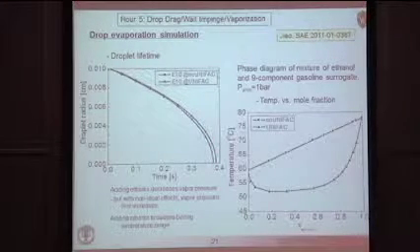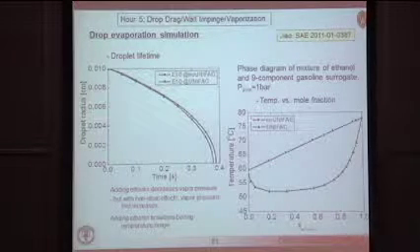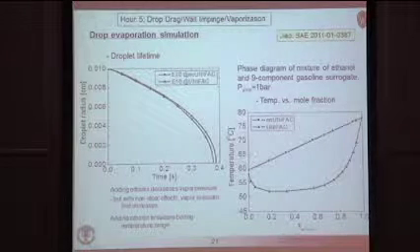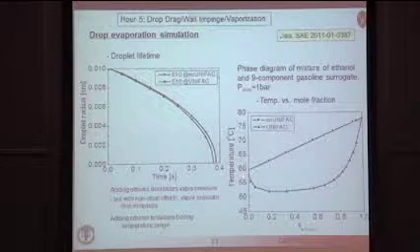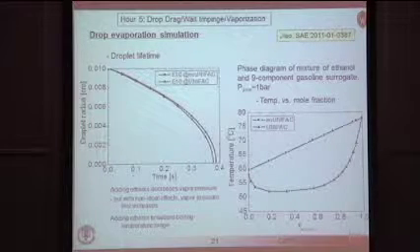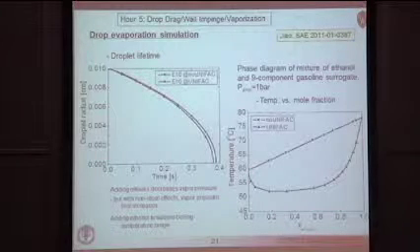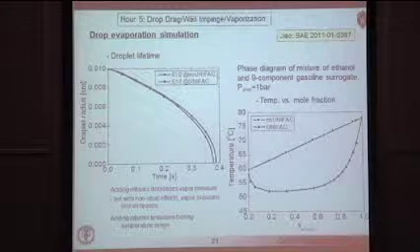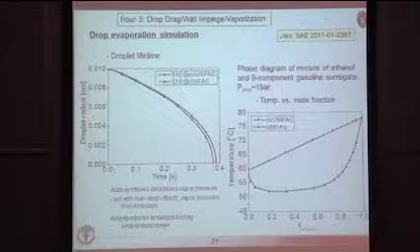But actually, if you look at the thermodynamics of what's happening, as shown on this plot here, which is the phase diagram, this shows essentially the boiling temperature of the gasoline ethanol mixture as a function of the amount of ethanol. So if we have no ethanol, the light ends of the gasoline start to come off around 60 centigrade with that surrogate list that I showed you. And if I don't account for the interaction, I get this linear increase in boiling temperature as I increase the amount of ethanol, whose boiling temperature is around 77 C.